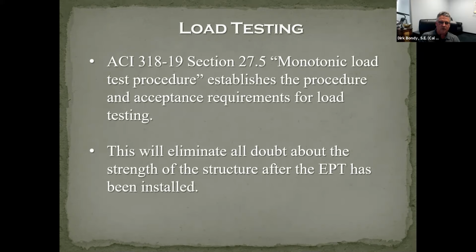One thing you can do and should consider doing is when you're done with all the strengthening, the concrete repair, the sealing, the external post-tensioning, is to ask for a load test. Ask the contractor to provide a load test, perform one. In United States dollars it runs about $20,000 for a testing company to run a load test. It will test the strength. It's actually a deflection test also.